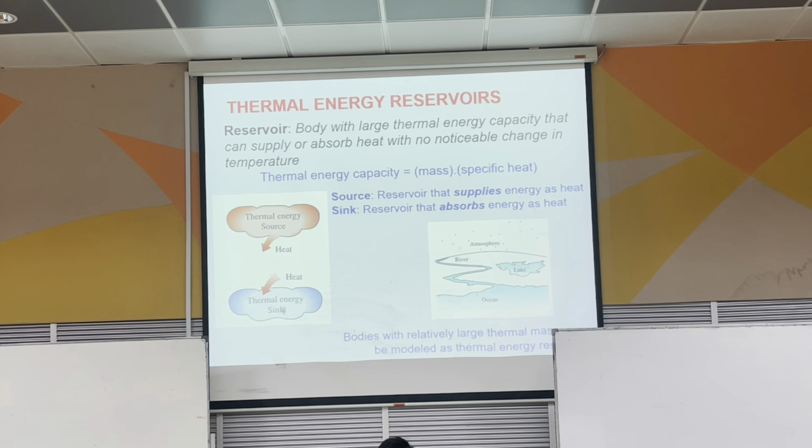The first part, the fan, actually is the diffuser. You need to slow down the air first, but we don't talk about them because they are not part of what we want here. So once it enters the diffuser, it will enter the compressor. What does the compressor do? The compressor will actually increase the pressure of the air, and at the same time it also increases the temperature slightly.